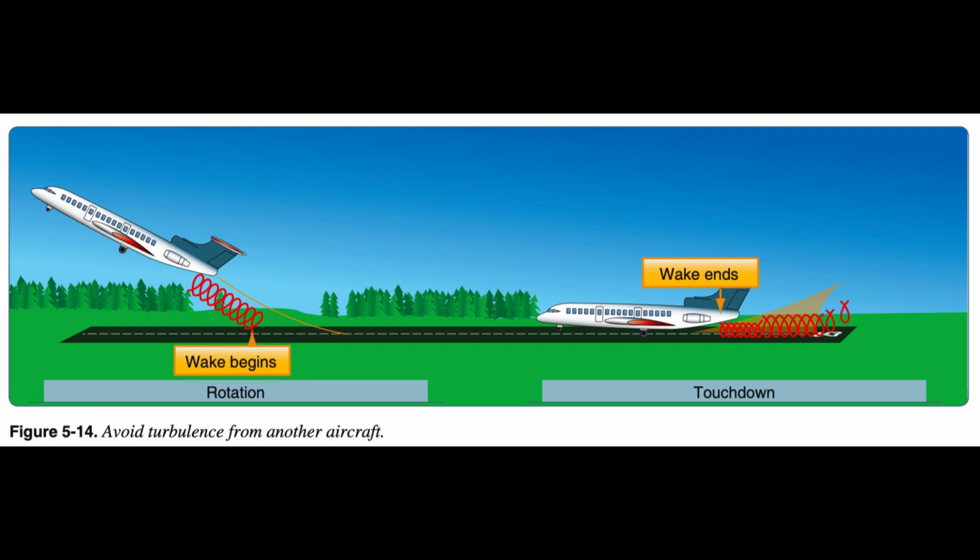Helicopter vortices should be avoided because helicopter forward flight airspeeds are often very slow and can generate exceptionally strong wake turbulence. Wind is an important factor in avoiding wake turbulence because wingtip vortices drift with the wind at the speed of the wind. For example, a wind speed of 10 knots causes the vortices to drift at about 1,000 feet in a minute in the wind direction.